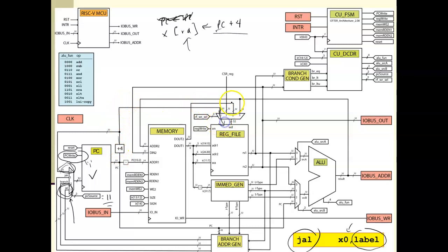I need to get that into a register, which means RF select here has to be 0, 0. And I need to turn the reg write on, which needs to be 1. Okay, so that, once again, this is the other part of the instruction that it's not overly apparent for this jump instruction, but it needs to be in there.